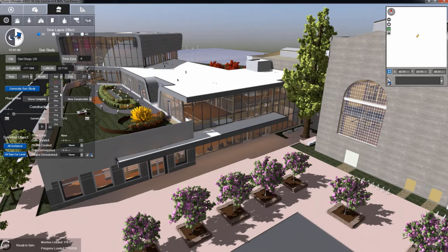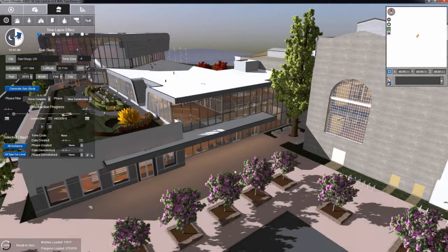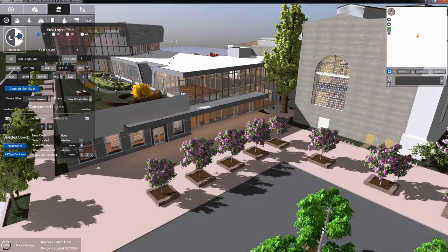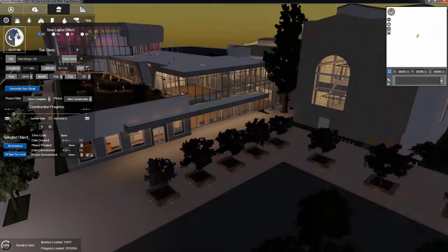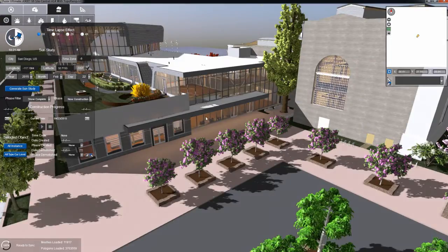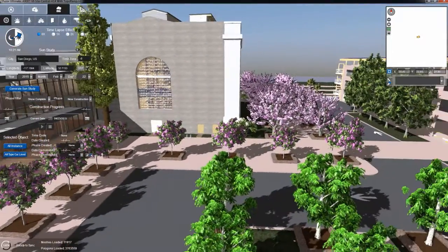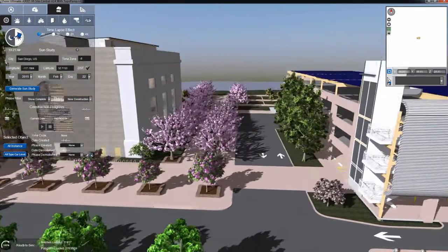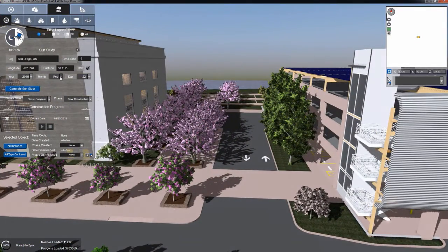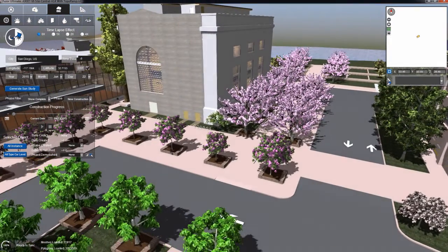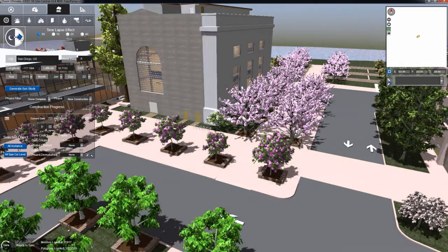Let's throw this back into February, see what the long shadows are looking like. There we go. Now in the previous video I went through the sun slider briefly. But the nice thing is, now that I've set this for position and day of the year, I can actually see what effect that's going to have. Let's bring that to June. Let's try the hottest time of the year, because that's really when this is going to matter. So San Diego, a lot of shorter shadows during that.